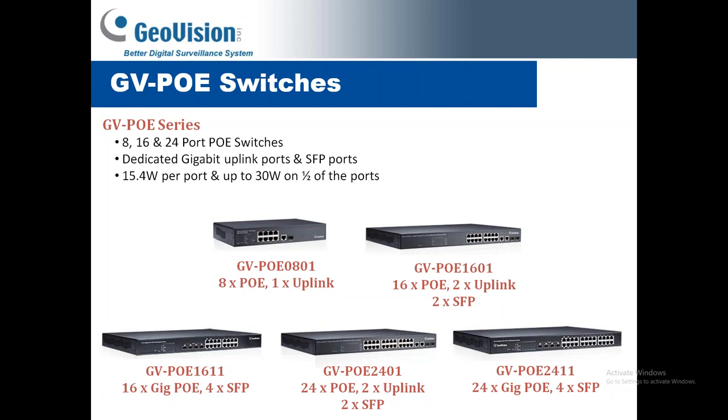GeoVision does offer our own line of PoE switches. We offer these in 4, 8, 16, and 24 port. Some unique things about our switches. The models on this slide here are all web managed. They also have a very strong power rating. You get 15.4 watts on each port, and then half of your ports can go up to 30 watts.